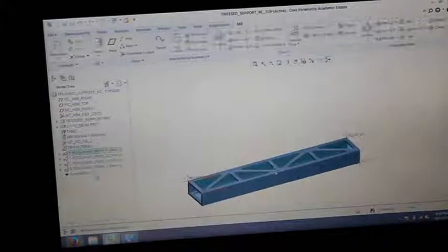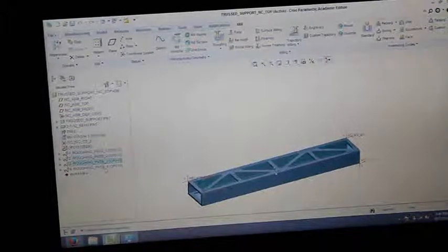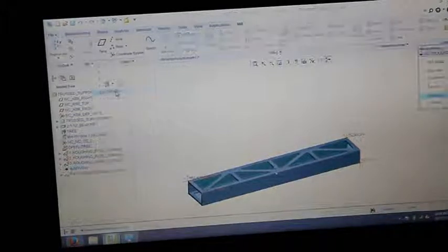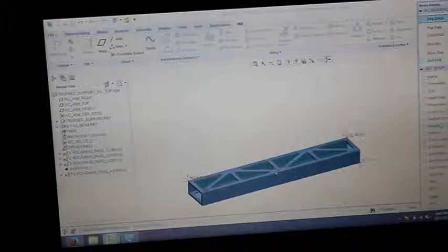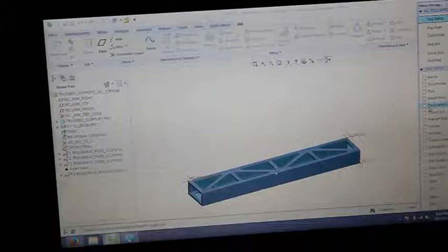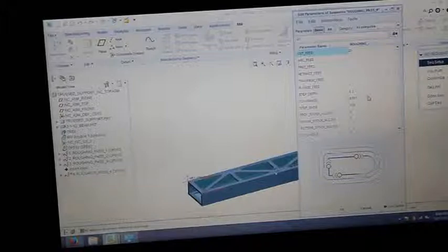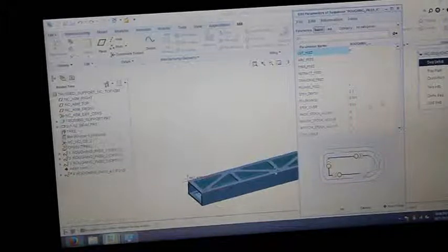So done sequence. These are all 3 finishing passes, and they're all roughly following the same template, so we'll just look at the last one. This is the final finishing pass. It uses tool 3, our smallest tool, and we can go and look at our parameters. So yet again, cut feed to 20. Step, everything is pretty much the same as it was before.